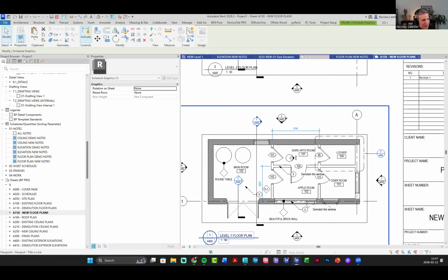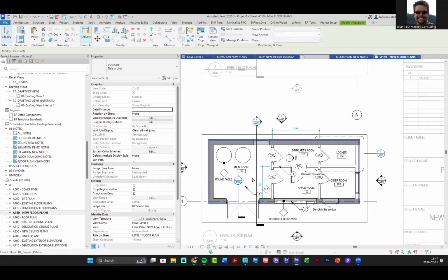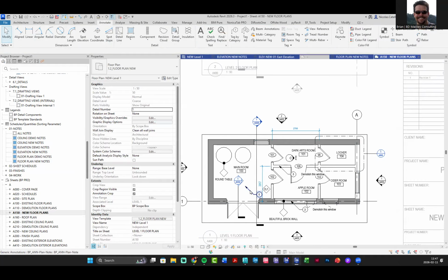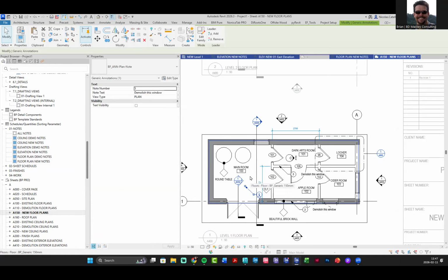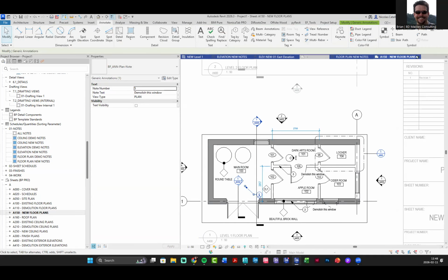I saw that a few times and I don't like it. It makes me worried. But even in that case, when you're pointing to a void, there's usually a floor or something there you can point to. You can also just grab a keynote, make it a user keynote, point to something, make sure the end is a free end, and you can move the arrow wherever you want. So it's six one way, half a dozen the other. Either way, if you're using keynote, you're still doing a user keynote, which means you're just pointing to something arbitrary anyway, and it doesn't really matter.